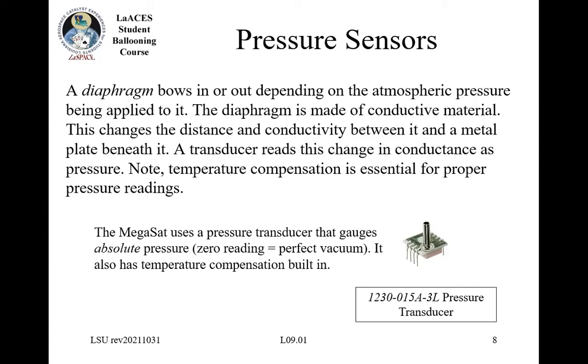for temperature. One thing that's important to note about pressure sensors: pressure is always a differential, just like voltage is always, this is X volts higher or lower than this, right? So with pressure, you're measuring the difference in pressure across the two sides. What we're going to use is called an absolute pressure gauge, which means that it's basically referencing the pressure in comparison to an absolute vacuum. So you can see there's a little tube here, and that's what's actually sensing the ambient pressure.